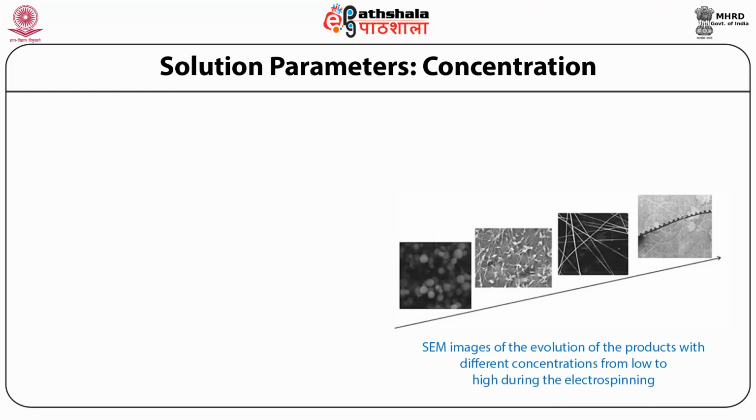Here, I want to discuss the several parameters which one needs to care about during electrospinning, for good quality growth of nanofibers. For the growth, working parameters are very important, and one needs to understand not only the nature of electrospinning but also the conversion of polymer solution into nanofibers through electrospinning. These parameters can be broadly divided into three parts: solution parameters, process parameters, and ambient parameters. Each of these parameters can affect the fiber's morphologies, and by proper control of those parameters, we can fabricate electrospun fibers with desired morphology and diameter.